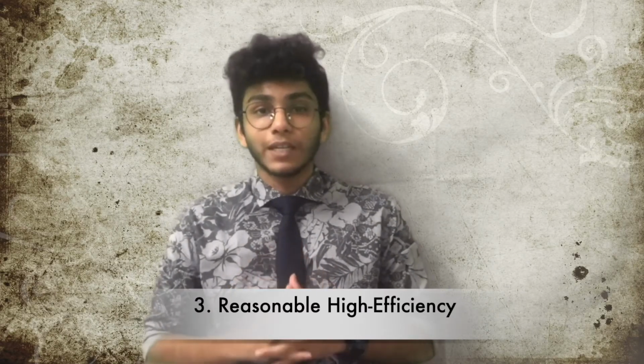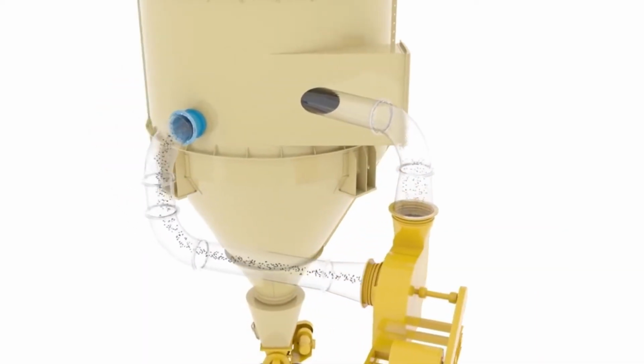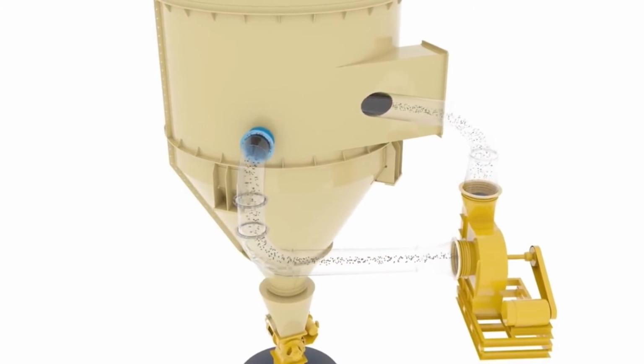Also, the costs of filter replacements are high, which when added to the cost of the third-party services may have a negative impact on the company's budget. In this scenario, using cyclone dust collectors, which are low on maintenance, is an economical option. Moving on to the third advantage, centrifugal collectors have higher energy efficiency. They have constant airflow delivery that enables them to reach up to 84% efficiency.